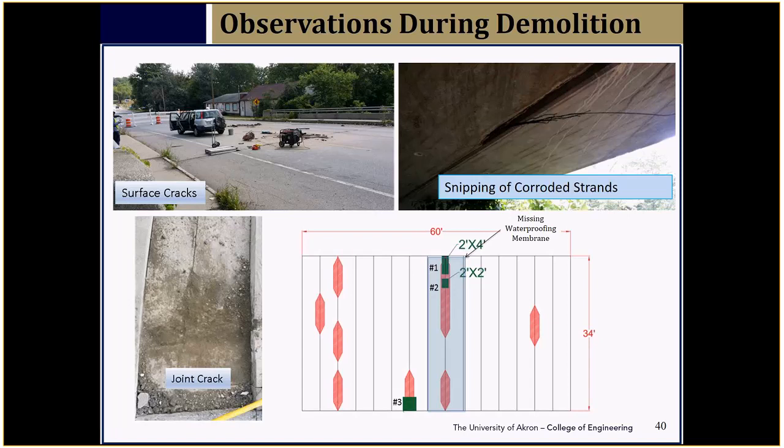Not in ODOT projects, but in other projects we found that if we use polypropylene fiber of 7.5 pounds, a slightly higher dosage, even in structural members, the tendency of the member to see corrosion damage is substantially reduced, by a factor of 2. So we proved that the service life of a reinforced concrete member can be increased by a factor of 2. That means I can double the service life just by adding fiber in the concrete.